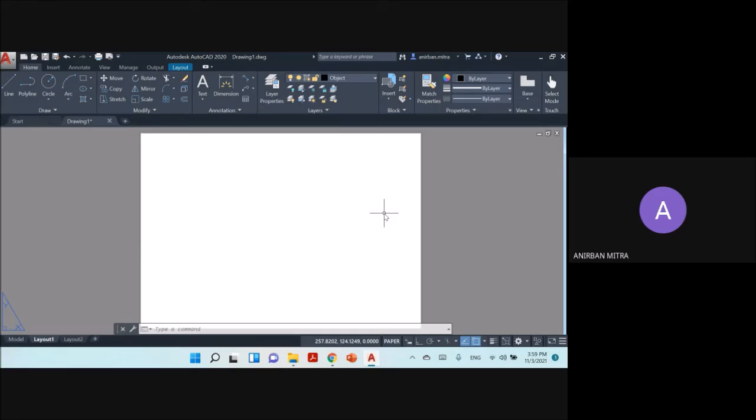So you can right now say that it is not associated with any kind of size at the moment, or if it is associated with a size, we do not know that. We have to confirm it from the page setup. How do you get to the page setup? You can write in the command prompt page setup. So that is the command to bring up the page setup manager.